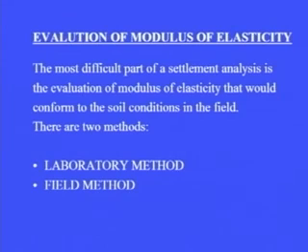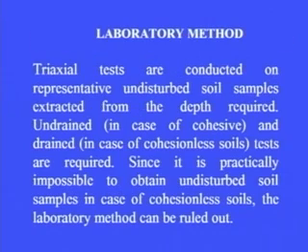Evaluation of modulus of elasticity. The most difficult part of a settlement analysis is the evaluation of modulus of elasticity that would conform to the soil conditions in the field. There are two methods available, one by laboratory and another by field in situ.